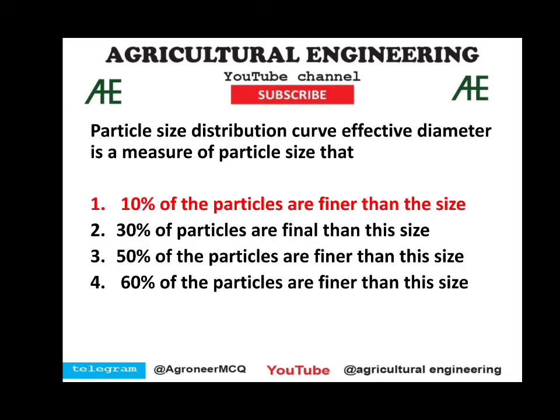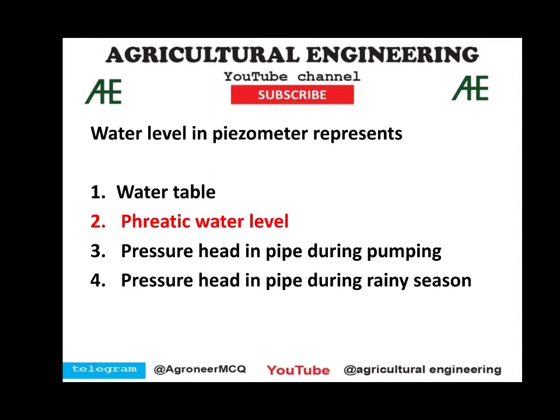Particle size distribution curve. Effective diameter is a measure of particle size, that is, 10% of the particles are finer than the size. There are a few terms, D60, D10. What is meant by that? It is nothing but the representation of particle size distribution, and D10 is representing effective diameter. Water level in piezometer represents phreatic water level.